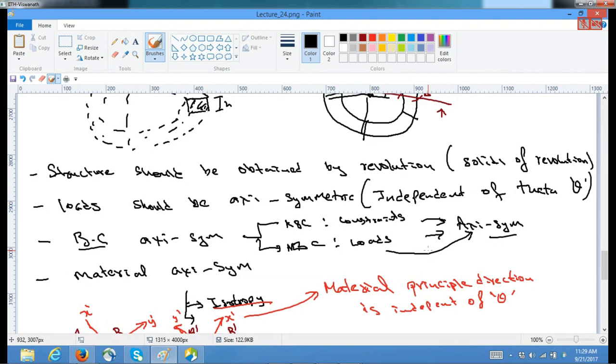I'm just giving an example; it would vary from problem to problem, but you can reduce your complexity drastically from 3D to 2D, and your solution is exact. It is not that you are approximating by not solving it in 3D. This axisymmetry is only a formulation that will still get you the same approximation as you would have with 3D. So it's only a reduction based on the symmetry rather than an artifact.